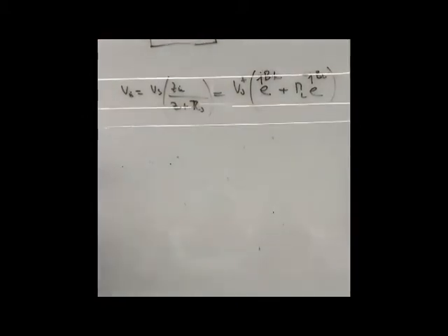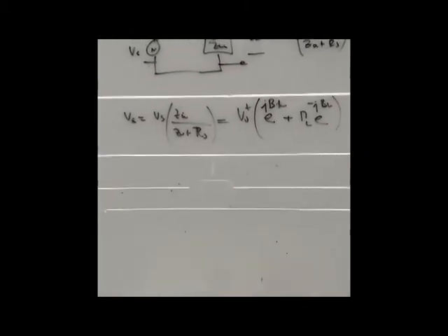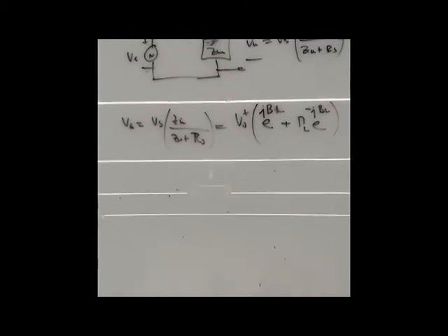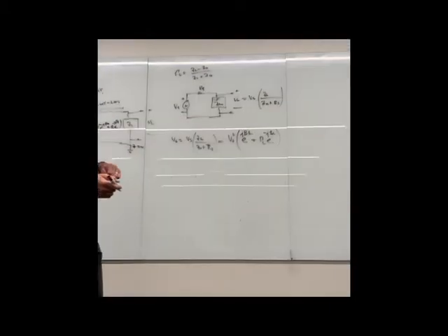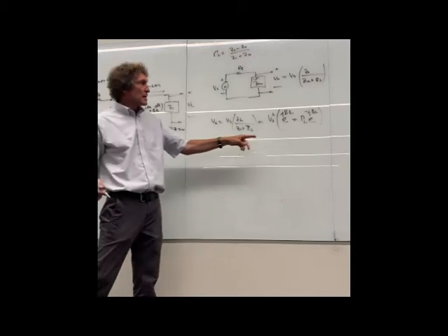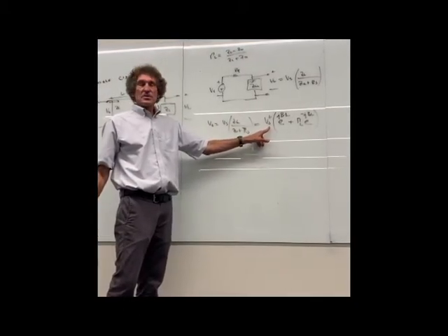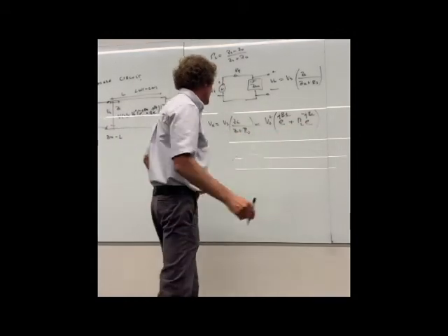So if we have a given transmission line, ZL is given, the length of the line is given, operating frequency is given, Vs is given, and Rs is given, we can calculate the reflection coefficient, and we can calculate Vn, and by calculating Vn, we can get V0 plus, can't we? We just simply divide by this on the other side.